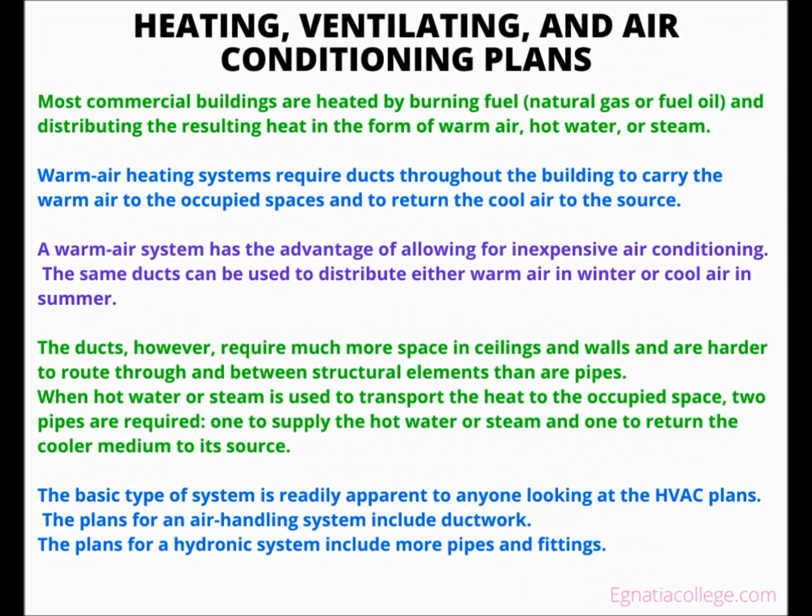Most commercial buildings are heated by burning fuel, natural gas or fuel oil, and distributing the resulting heat in the form of warm air, hot water, or steam. Warm air heating systems require ducts throughout the building to carry the warm air to the occupied spaces and to return the cool air to the source. A warm air system has the advantage of allowing for inexpensive air conditioning. The same ducts can be used to distribute either warm air in winter or cool air in summer.